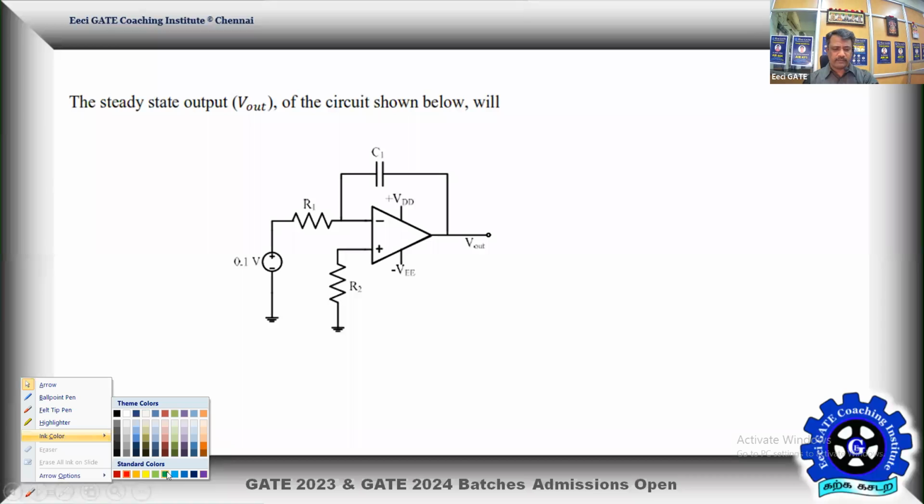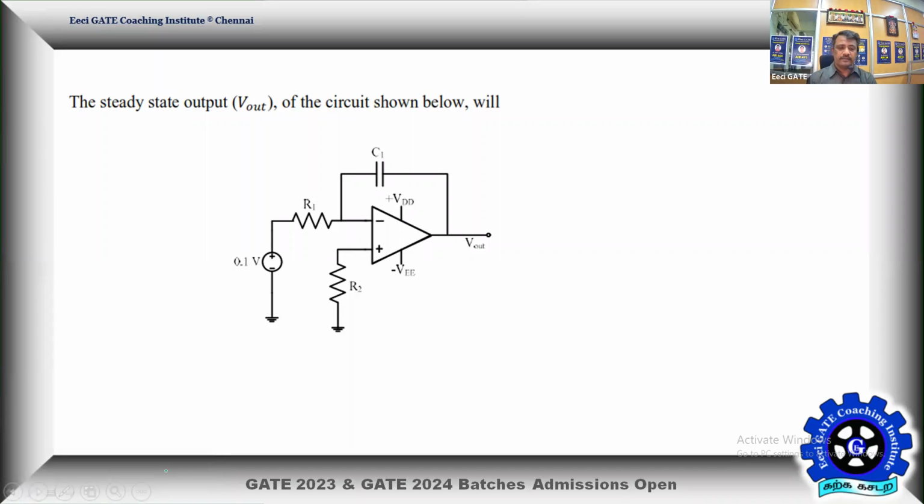So perceiving the problem in another way, since the op amp is not mentioned as ideal, let me assume there are bias currents as well. Let this be IB1 and this be IB2. There are bias currents for the op amps. Again, assuming virtual ground is not exactly possible here, because there is going to be some potential, call it Vx, and there is a current in this.